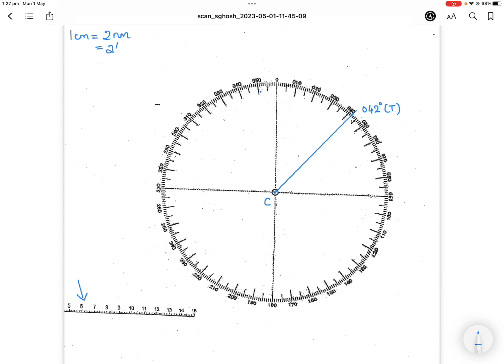So you can see here this dot represents the letter O. This is the origin. This is when I got my first plot at 0640. The distance OC signifies 11 nautical miles. Now because I have chosen a scale of 1 centimeter equals 2 nautical miles, this is 5.5 centimeters, which in my case denotes 11 nautical miles. If you have chosen a scale of 1 centimeter equals 1 nautical mile, you should be measuring out 11 centimeters in the direction of 351. And the first plot is called O, that is the origin plot.